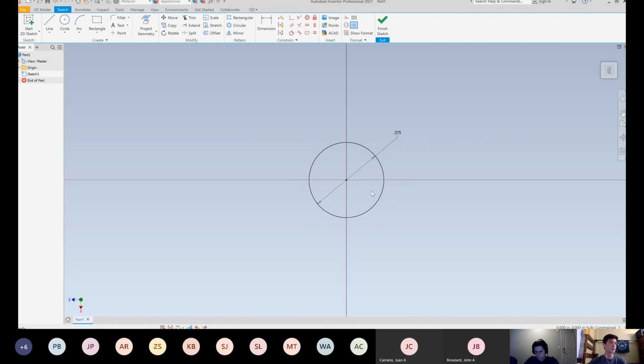So now we're going to create another circle. And so I'll just left click here in the center again. And when you hover over, and it kind of snaps into place with the green, the green means it's trying to snap into a particular geometry that it's guessing you want, which is correct. I do want the center here.